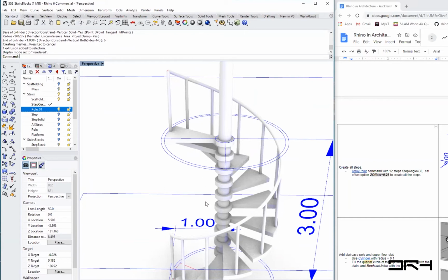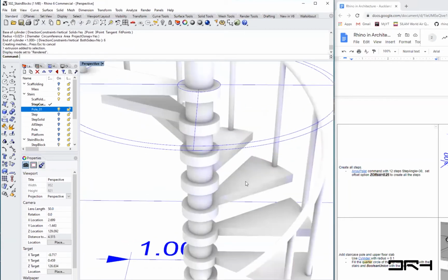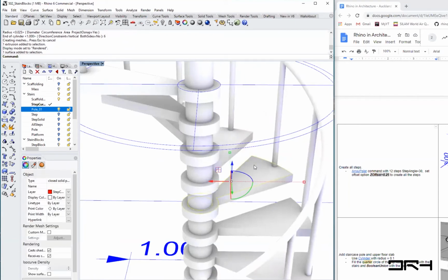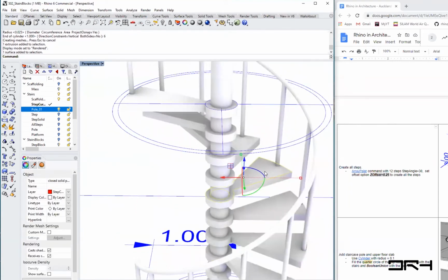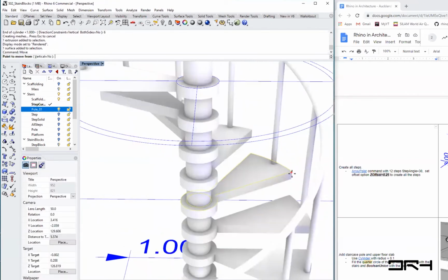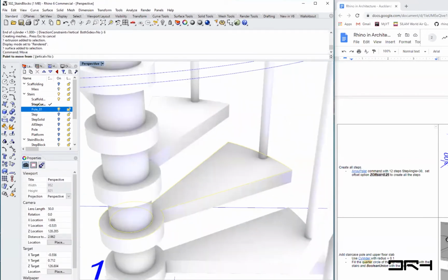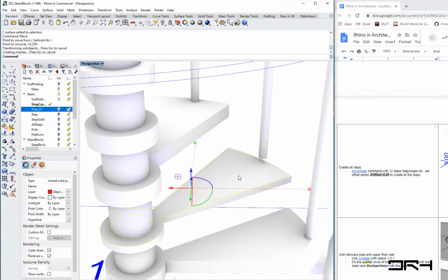The other thing is, if I want to change, for example, the thickness of the step, and you select that step and move it to make it thinner, from here to here, you see that I affected only one step while the rest continue to be the same thickness. So this is very limiting, and you see that the handle is also not in the proper location. This makes the editing more cumbersome, and you'll have to do remodeling basically.